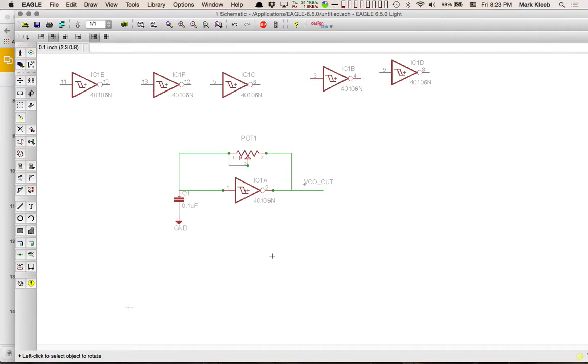There's another problem with our circuit so far, discounting the counterpart that we haven't gotten to yet. What's missing from the 4106? Power. No power and ground, right? For almost every chip, Eagle won't display power and ground unless you want to see it. I like to see this in my diagram. Also, I'd like to know where they're connected to on the board.